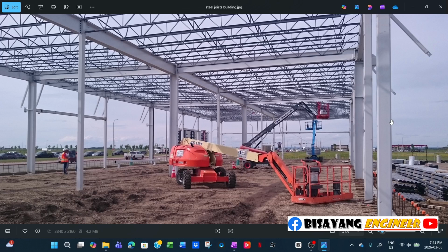And then the problem with this is in between columns there is always a full height window. So there's no way. I mean, you can put cross bracing, but the client doesn't like any bracing at all. So everything is moment connection.